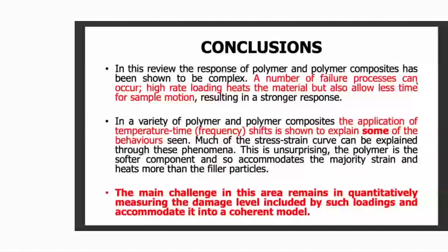In a variety of polymer composites, the application of temperature-time-frequency shift has been shown to explain some of the behaviors seen. So we can make a reasonable prediction of, say, flow stress versus strain rate. And that's absolutely fine.